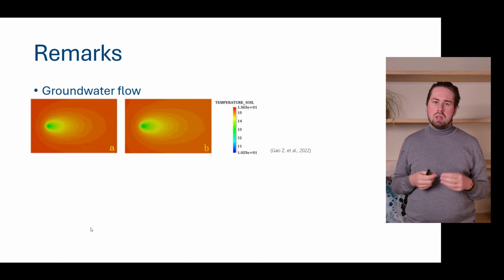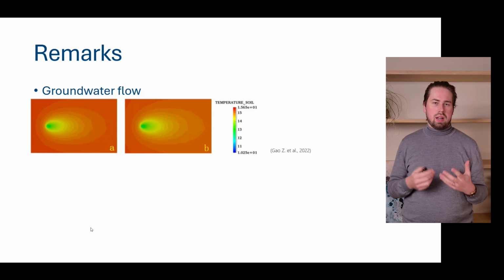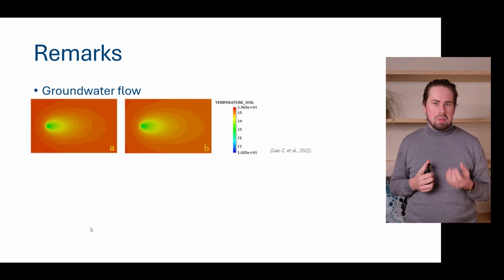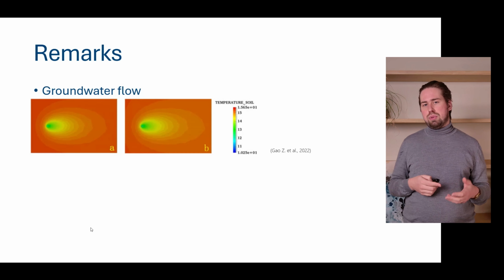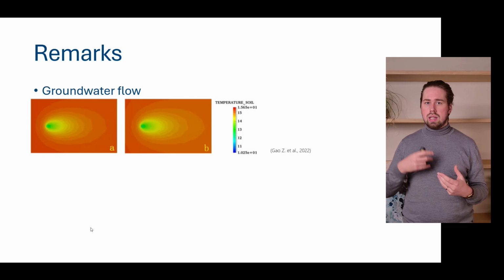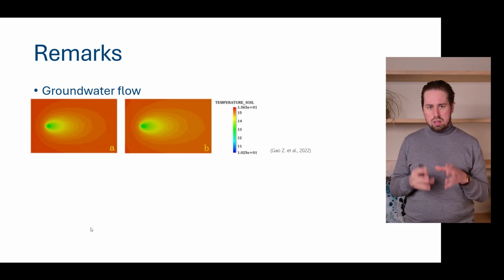Now, perhaps you say, well, this groundwater, how do I know it? Where can I find information for it? And that's exactly the problem. It's really complicated to take this into account. Perhaps you have to do measurements and so forth. And you also need very detailed numerical simulation tools like Sequent or ModFlow or FreeFlow to take this into account.